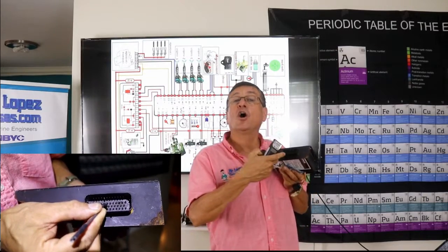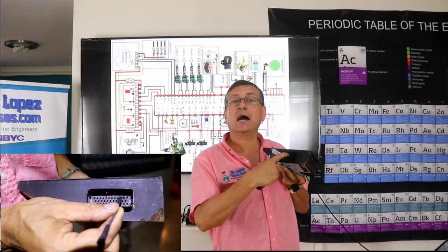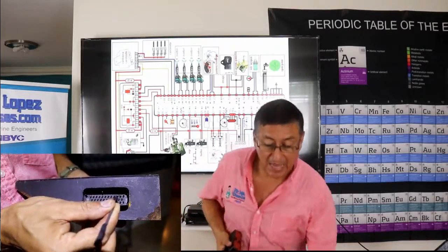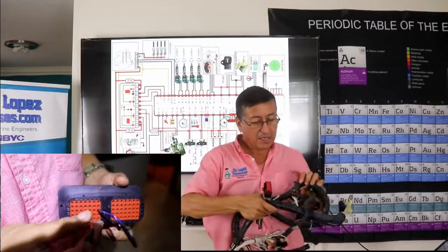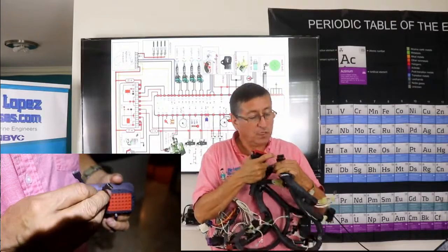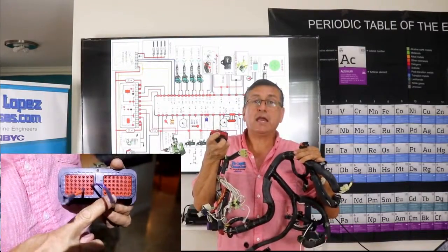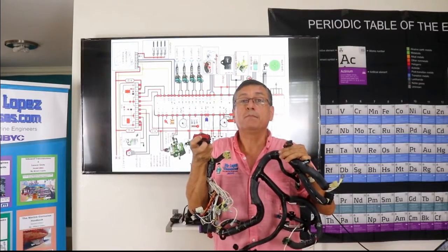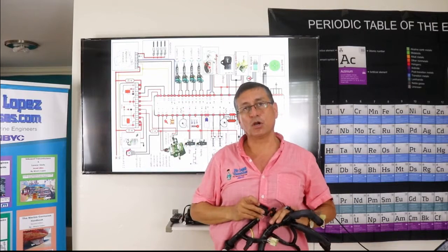I am going to open the ignition switch and check if I have power in that pin. I have power in that pin. After that, I am going to check the harness between the pin and the sensor. I am going to check continuity between the middle pin and pin 17. Okay, I have continuity. Beep. No beep, and the harness is not good.